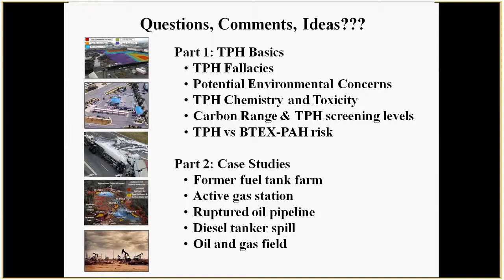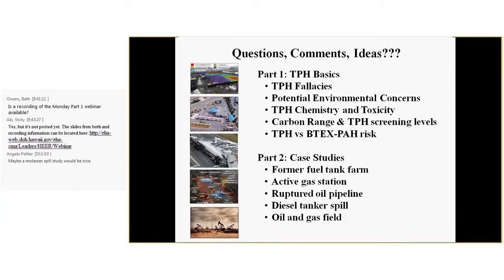The issue is that for initial comparison to screening levels, we pretty much have to assume at this point that the hydrocarbon degradation products have the same toxicity as the parent compounds. So you want to compare the non-silica gel data to your screening levels initially. But I always get both. It's good to document degradation and that Mother Nature is taking care of things at a site, probably better than you can do by injecting stuff into the groundwater or other types of treatment.